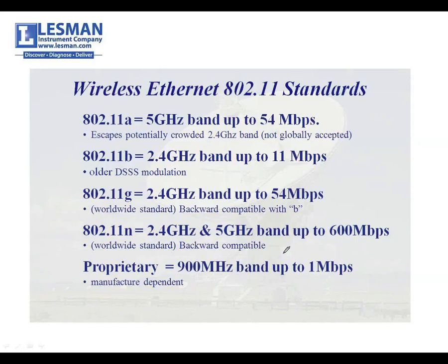What their concern is that you might be stepping on their signal, okay? And if you get them involved, tell them what you want to do, ask them what their concerns are, we can usually overcome them. Often the 2.4 gigahertz band, they're very protective of, and they'll say, I don't want you to use anything industrial on 2.4. That's why we offer both 5.8 gigahertz and 900 megs, so we can work around that opportunity.